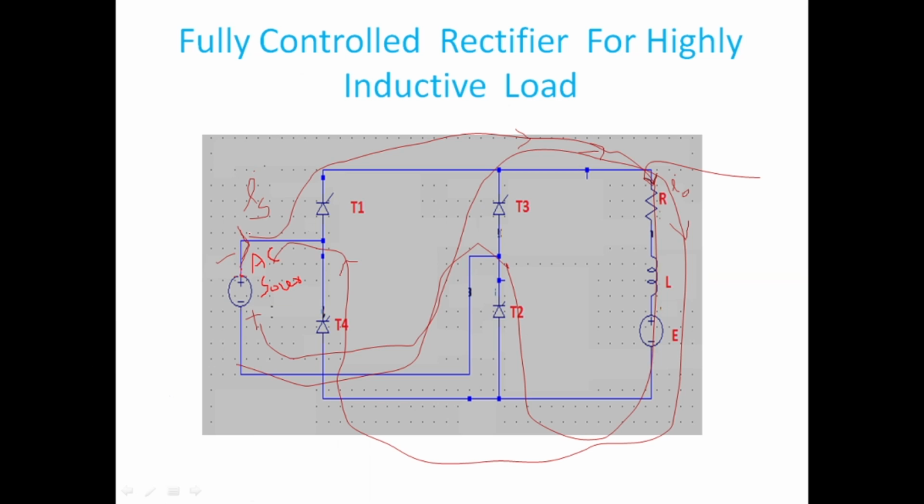If the current is flowing in the arrow direction, I will say it is positive. At any time if the actual current is going opposite to this arrow, I will say it is negative. Always the positive or negative of current depends on the arrow we are considering for reference. Right now I am considering this as my reference, and this as positive.